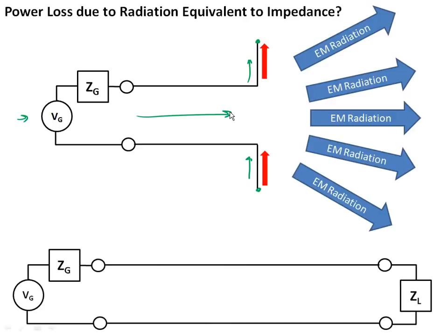So in fact, we do have this situation as shown here. If we drive a transmission line with an AC source and couple it to an antenna, that antenna acts like a load, but instead of turning the radiation to heat or mechanical motion or driving some other circuit, it sends all that power out, if it's a good antenna, into space. And this idea of an antenna having an impedance, and being a device that we put at the end of a transmission line that turns AC voltage and current into propagating electromagnetic waves, is exactly what we want to study when we start to learn about antennas.